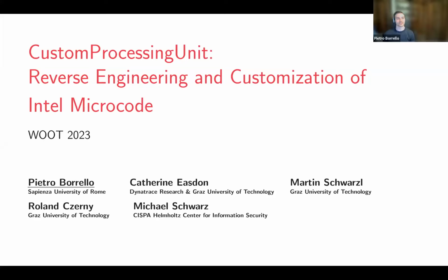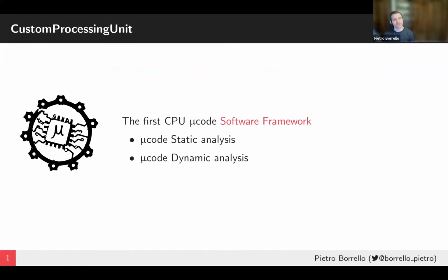I'm Pietro, and today I'll talk about custom processing unit, reverse engineering and customization of Intel Microcode. I'm actually very happy to present this talk. In this talk, I'll present you custom processing unit, which is the first microcode framework for full CPU microcode static and dynamic analysis, all via software.